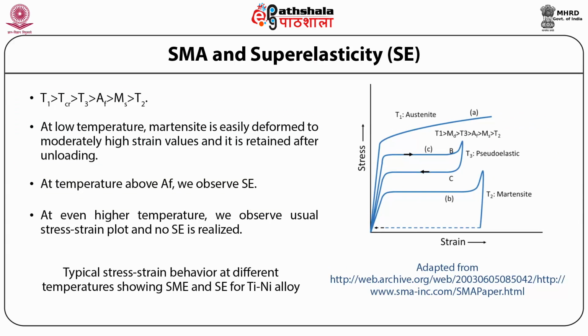SMA and superelasticity. So now, students, the question arises: how does this plot change when the temperature is changed? The answer to this question is this plot. At intermediate temperature, that is slightly above AF, superelasticity or SE or pseudoelasticity is observed, as seen in the curve C.